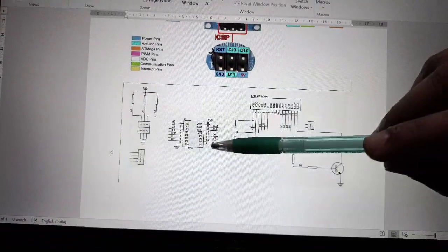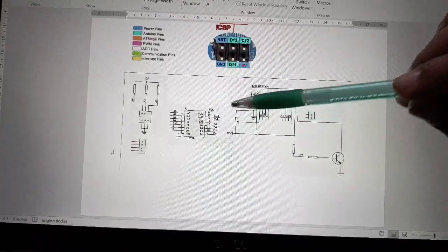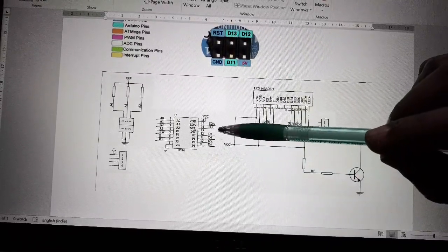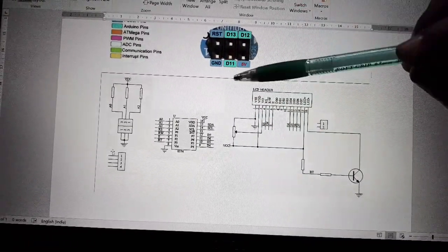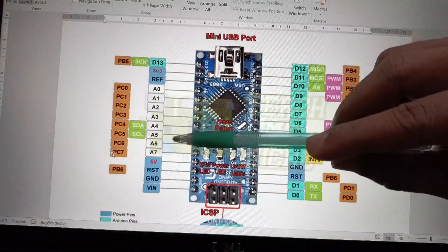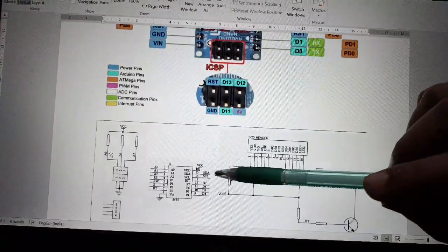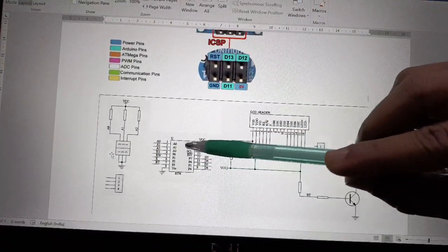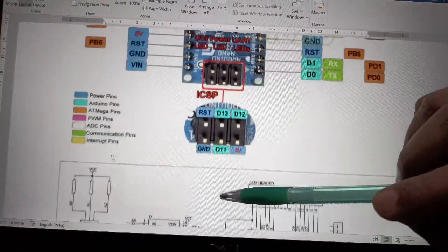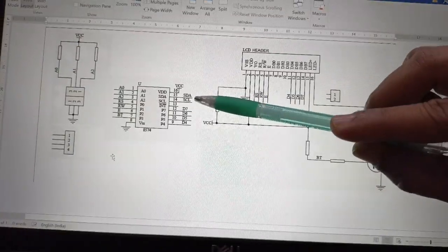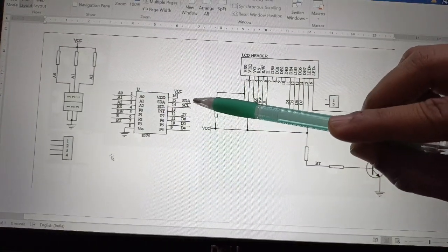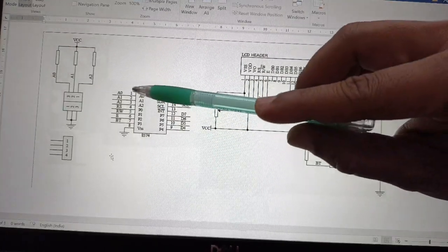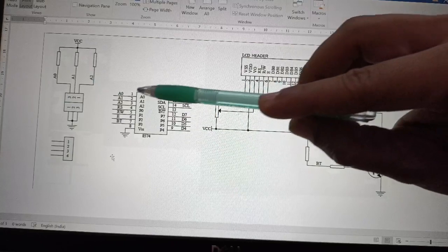So here the PCF8574 board circuit diagram is this. When we zoom in, you can see SDA and SCL. The A4 and A5 from this Arduino Nano board are connected with this SDA and SCL of the PCF8574, which is an I2C to parallel data transfer IC. Once again, if you zoom in, you can see more clearly. Here you come to this PCF8574. This is the protocol converter IC. So I2C data goes in, the parallel data comes out. You can see D4, D5, D6, D7 and D0, D1, D2, D3. So this IC does I2C data to parallel data transfer.